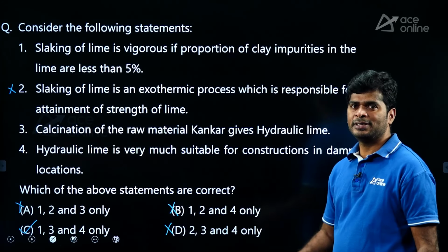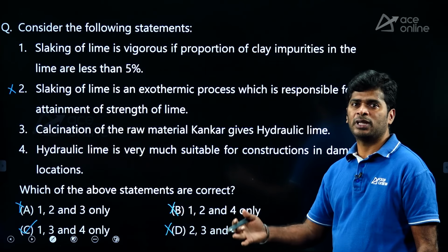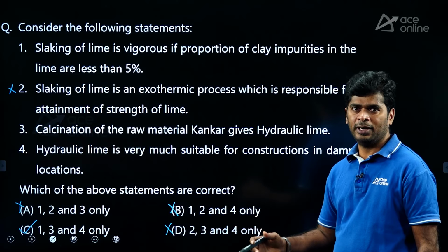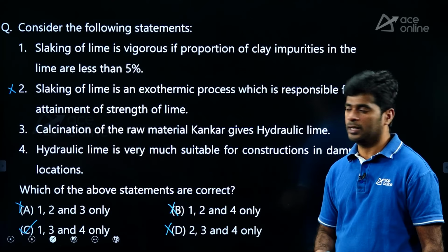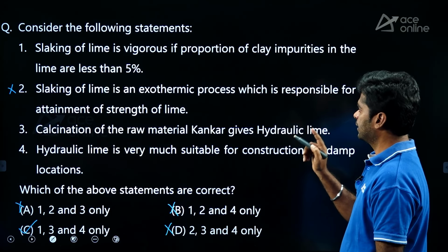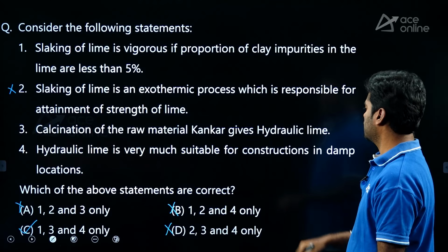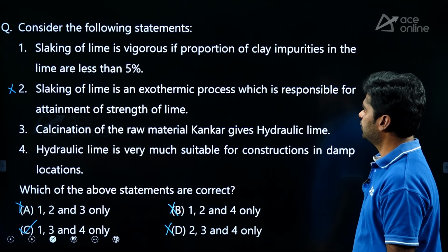Okay. Slacking is nothing but adding water to the lime, right? That process. It is not responsible for setting time, not responsible for hardening. So, option C correct. 2 is wrong. Rest of the statements are correct. Next one.